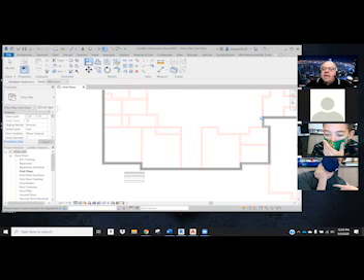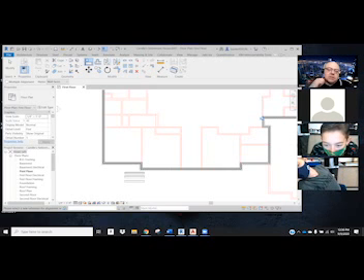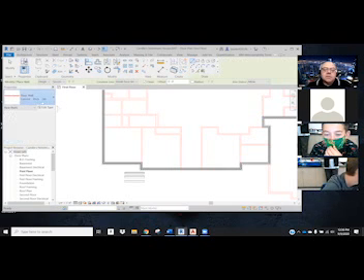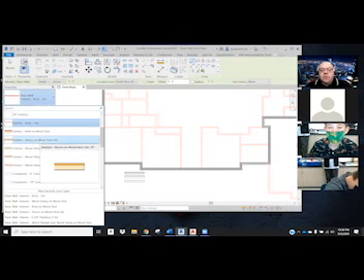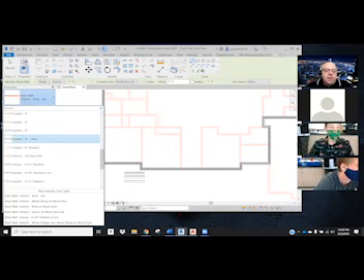And if you don't do that now, we can fix that later. It's really quick and easy to do. But we're going to do our partition walls, and they're already set up for you in your template. So architecture, wall, scrolling down through. And in fact, commercial, yours are kind of set up for you as well. So I'll show you that for you.